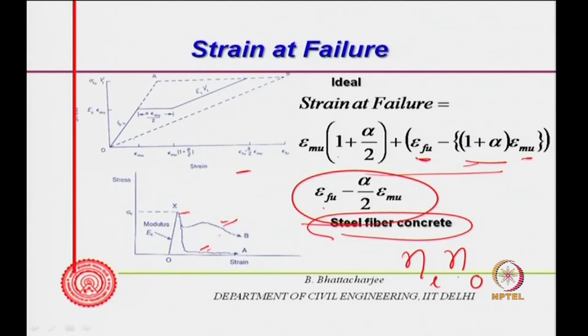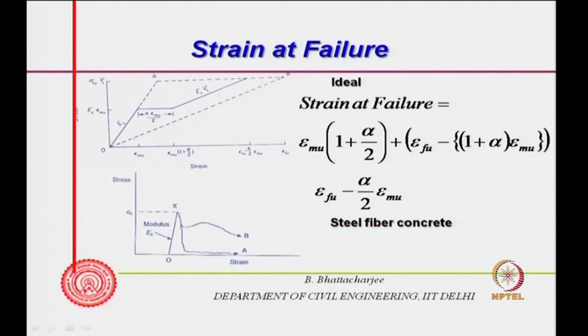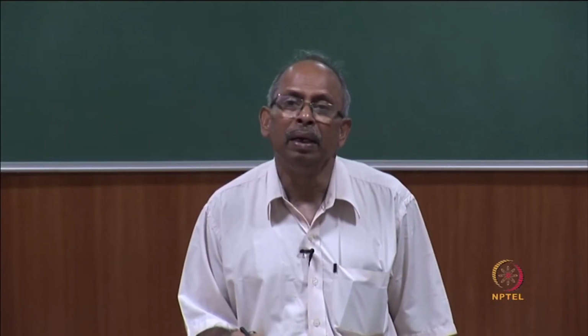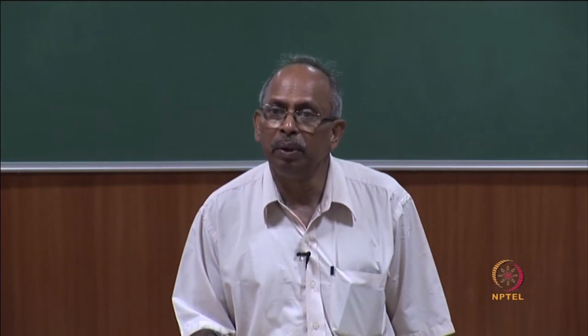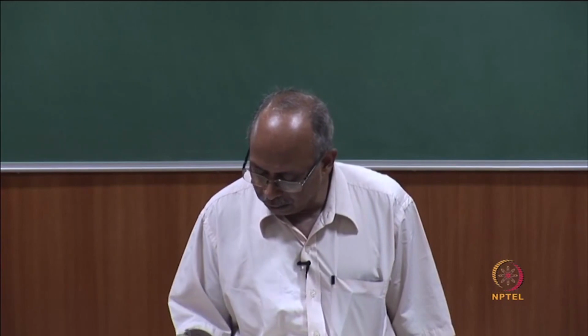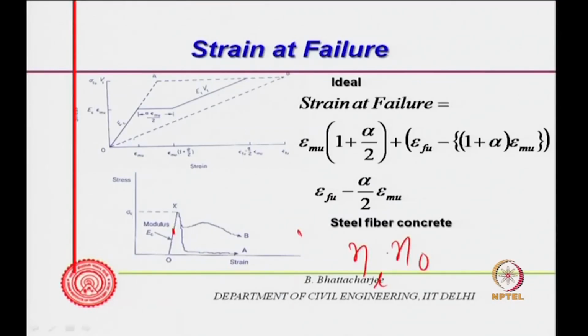So, you have just looked into the crack width for aligned fiber. Let us look at the stress strain diagram for aligned fiber, and then for real fiber, because for real fiber the modulus of elasticity would be multiplied by this, and after that also it may not be able to take the load, which may be less than that. So, the load it can carry would depend upon its Ef and the Vf content, which could be low.